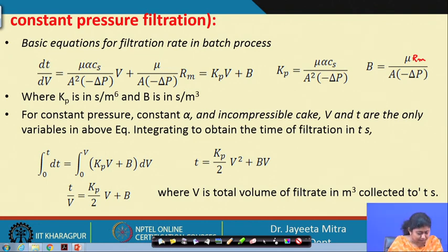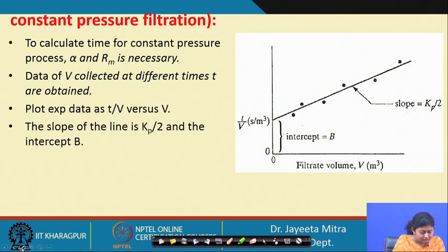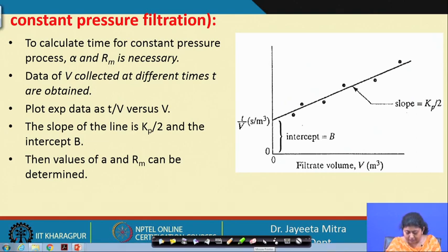Okay. So, this is how, for the case of a constant pressure filtration, we can calculate the time and all other parameters, like the specific cake resistance and the resistance due to the filter media.